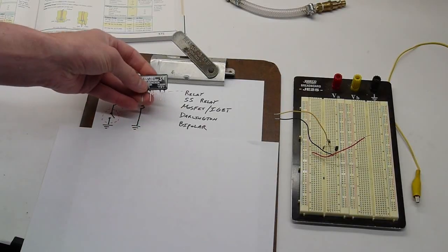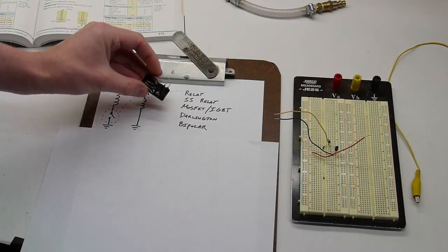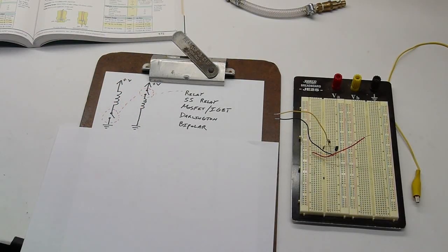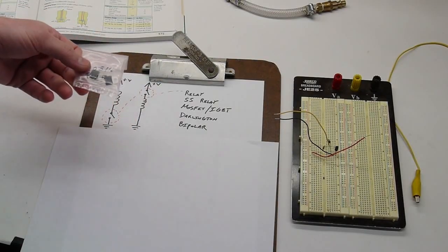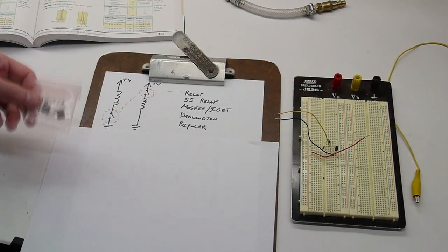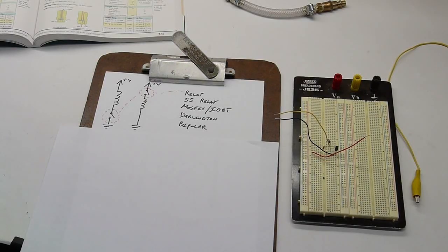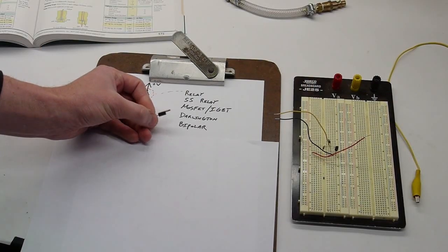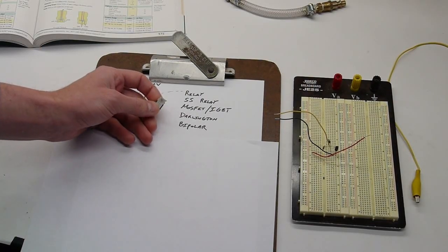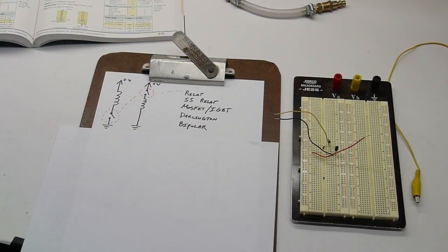Similarly, a solid state relay, also a very cool component, mostly used for isolation and high voltages or high currents. So save that one. A MOSFET or an IGBT, also for much, much higher currents. They don't isolate. Well, I guess they sort of could, but we're not going to use these today either. A Darlington transistor. This is actually not a bad choice. Today we don't need to use a Darlington, but I think I'll probably do a video on these later because they actually are quite useful in some circuits, generally for higher current stuff.